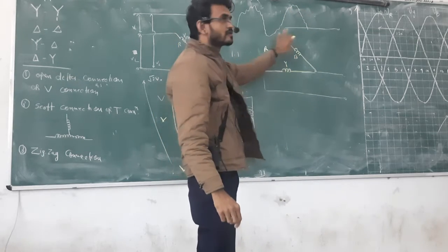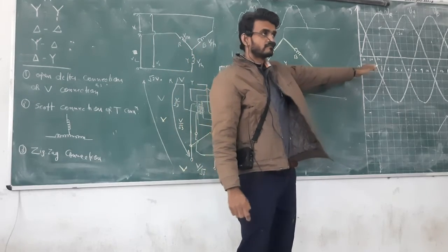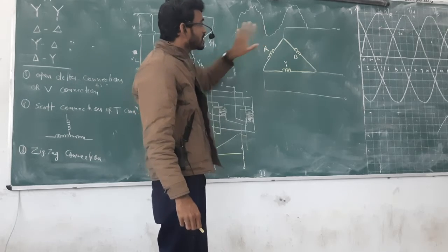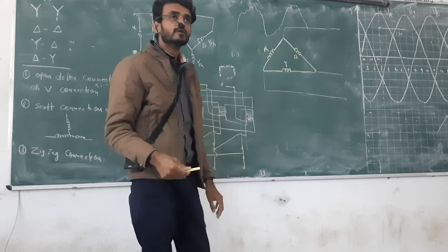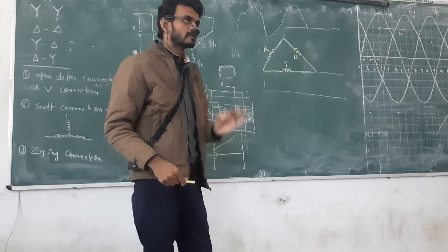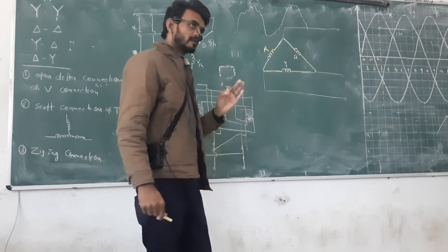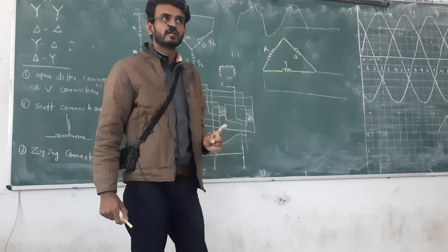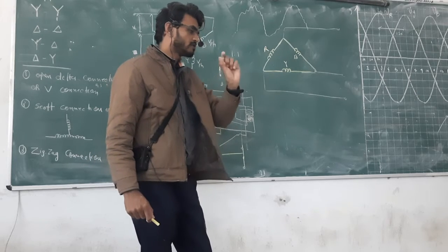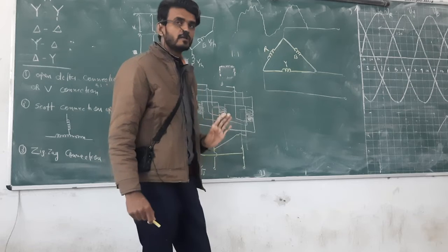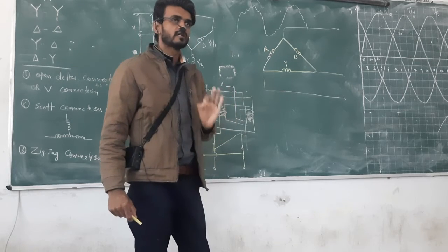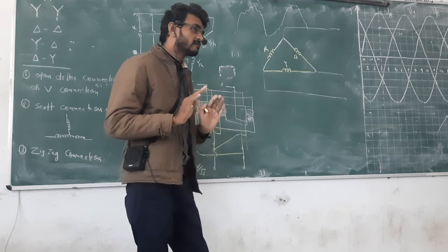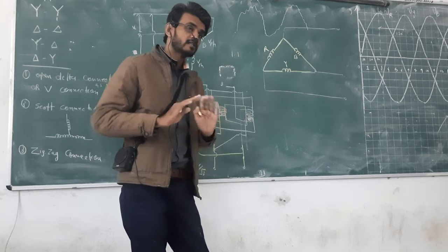In real life, the wave is not a perfect sine wave. This kind of waveform can be made up of a number of different sinusoidal waves with different magnitudes and different frequencies. If you add all those sinusoidal components together properly, you can get any kind of distorted waveform.